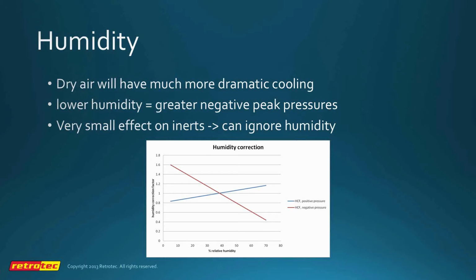If we discharge at a very high humidity, we get almost no negative pressure spike at all. And this is because with a halocarbon, the negative pressure spike is caused by, essentially you could say, evaporation, where the agent starts as a liquid and then flashes to a gas and causes cooling. And when we have a very, very high humidity, as you know, we have very little cooling, so we all know that from our own personal experience.